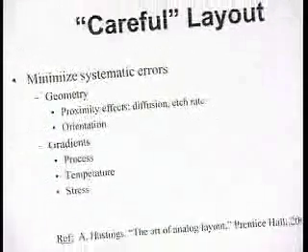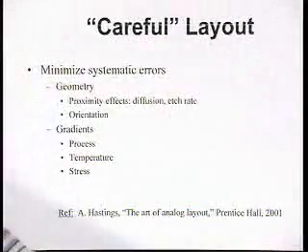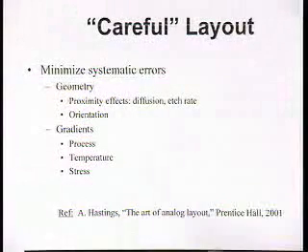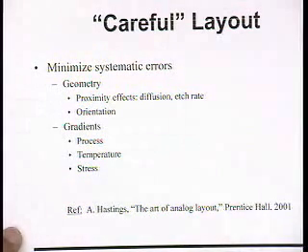Doing good layout is also helpful, and we'll go through some layout techniques relatively quickly. We talked about some of this in the beginning of the class, and I think I'll just highlight those things again just to remind you. So when we're doing layout, there's a lot of tricks, let's say, clever things that you can use to minimize matching errors, basically minimize systematic errors especially.